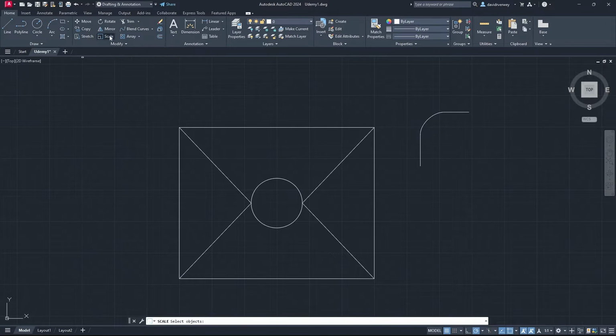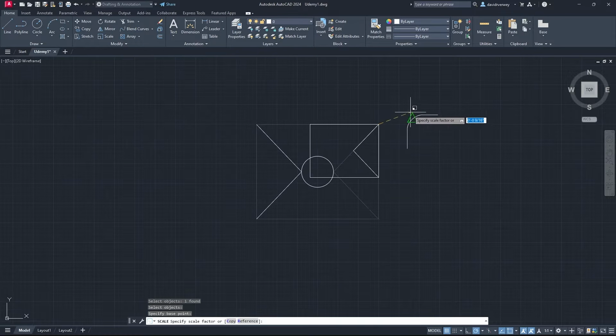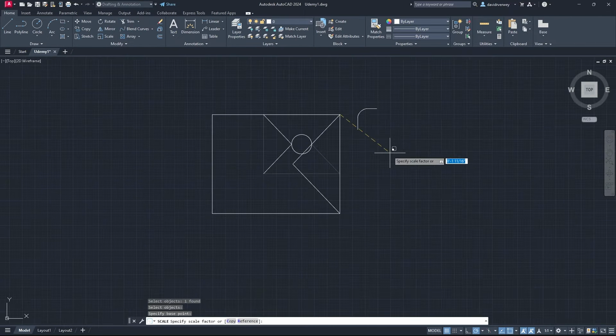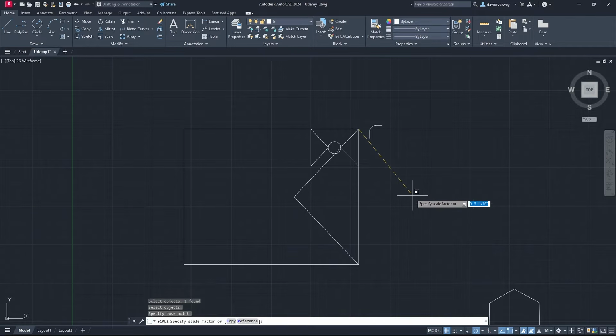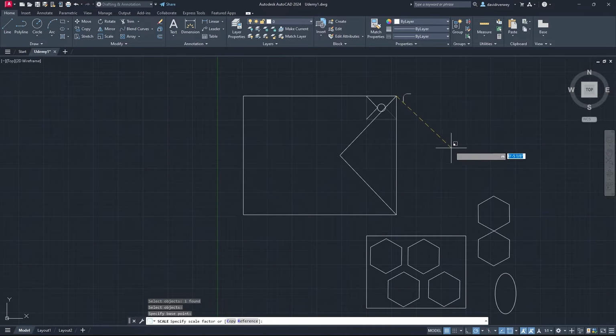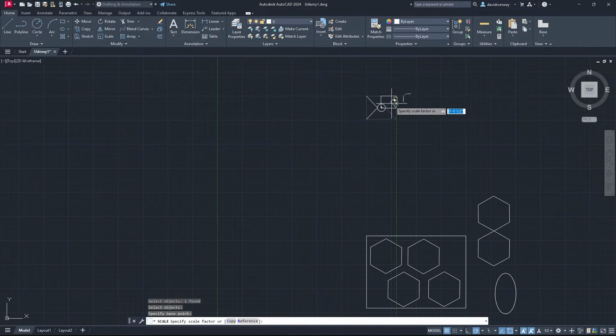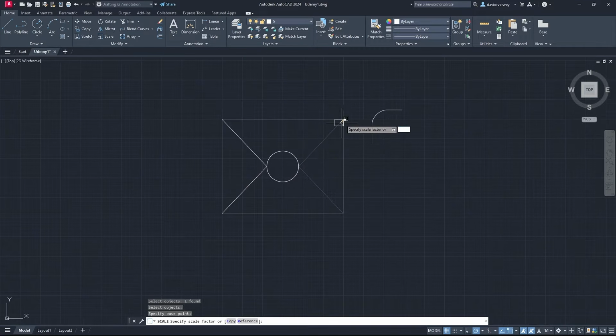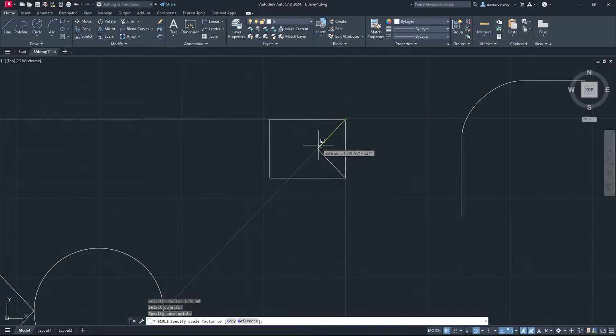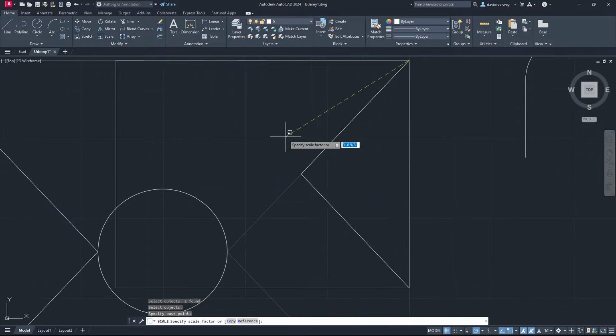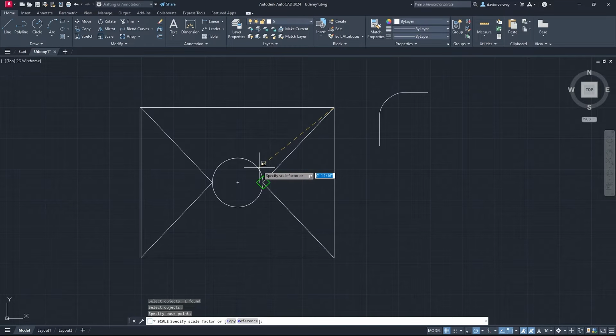We're going to just put it back to where it was, and once we move on from stretch, we've got the scale command. Scaling is kind of the same as stretching, except you scale from a corner. So what we're doing is we're scaling our object now. You're going to see we don't have it perfectly united. That's okay. We're just learning the commands right now. And you're going to see that scaling scales relative to where you select. So when you're scaling, if I click the corner, you're going to see that it's scaling relative to the corner of the drawing. So it's growing in proportion to the corner of my drawing.